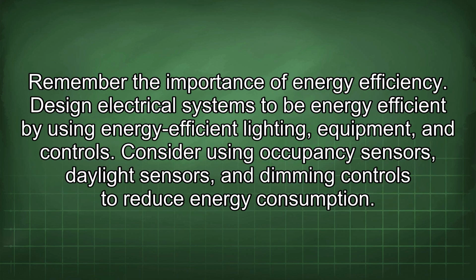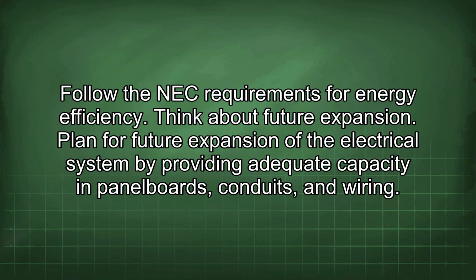Remember the importance of energy efficiency. Design electrical systems to be energy efficient by using energy-efficient lighting, equipment, and controls. Consider using occupancy sensors, daylight sensors, and dimming controls to reduce energy consumption. Follow the NEC requirements for energy efficiency.